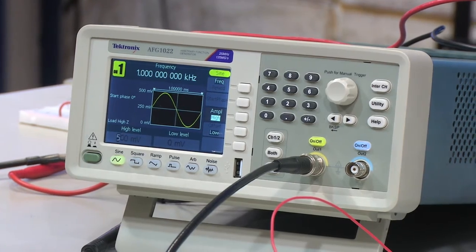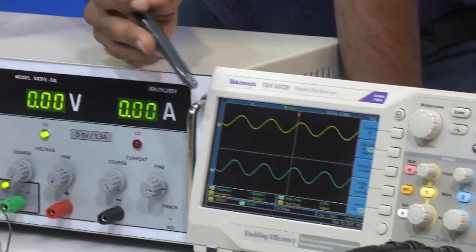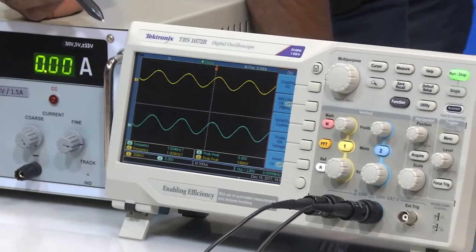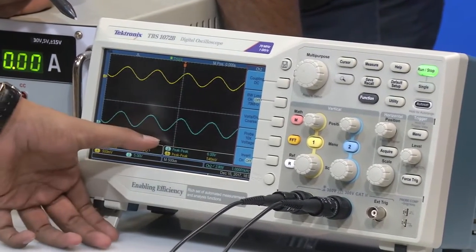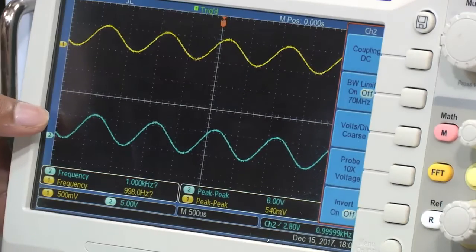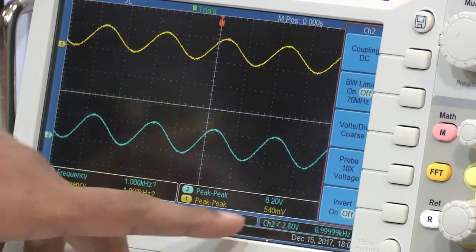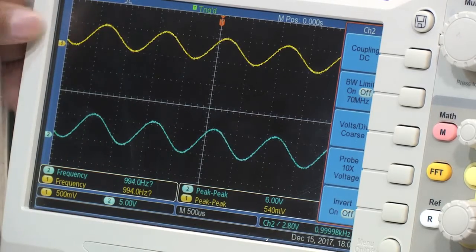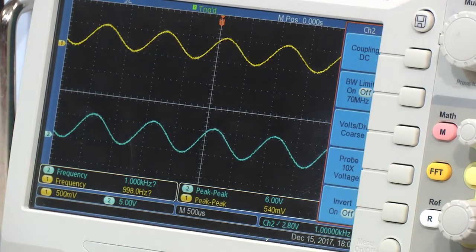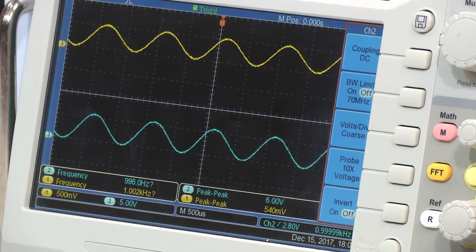What do we see at the output? We see at the output this input into gain, right. So, we see about 6 volts, 6.2 volts at the output, you can see the blue color thing, right, 6.2 volts at the output, and the input is yellow, one peak to peak 540 millivolts. That means still the output has not been clipped. So, 0.5 is okay, right.